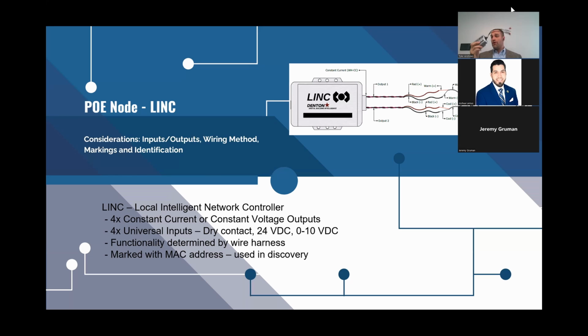Thank you. So 4 outputs gives you the option to do, for example, if you're looking at the screen right now on the wiring, you can see I have 2 outputs used on one fixture. Those 2 outputs would be a warm, cool light fixture where I want to change the color temperature. And you will be doing that in your class today, both on Zoom and live.